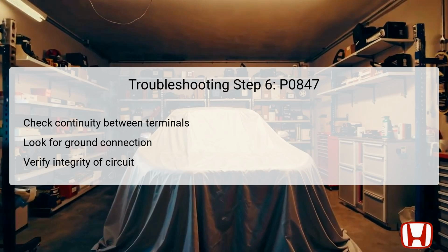If continuity is absent, it indicates a flaw either in the wiring or the connectors obstructing the operation of the transmission system. Confirming this continuity effectively diagnoses if the original symptoms are indeed due to wiring problems or faults elsewhere in the transmission circuit. This crucial step solidifies the connection integrity and impacts the overall success of repairs undertaken.